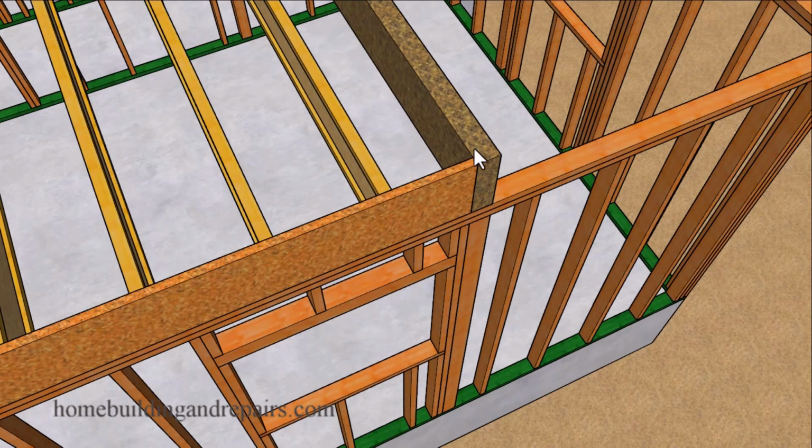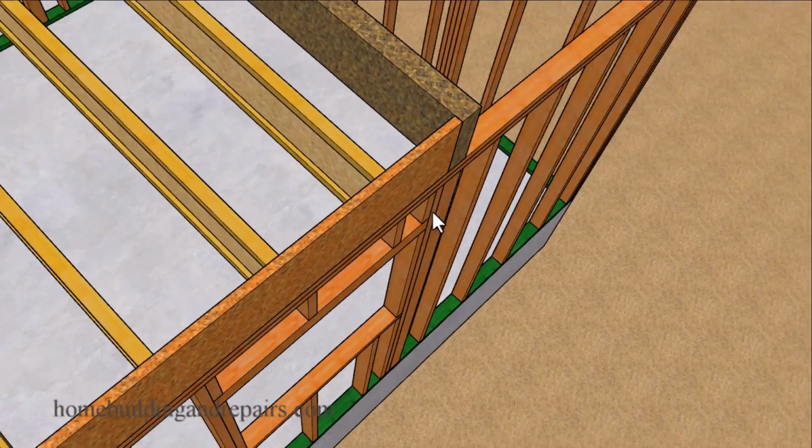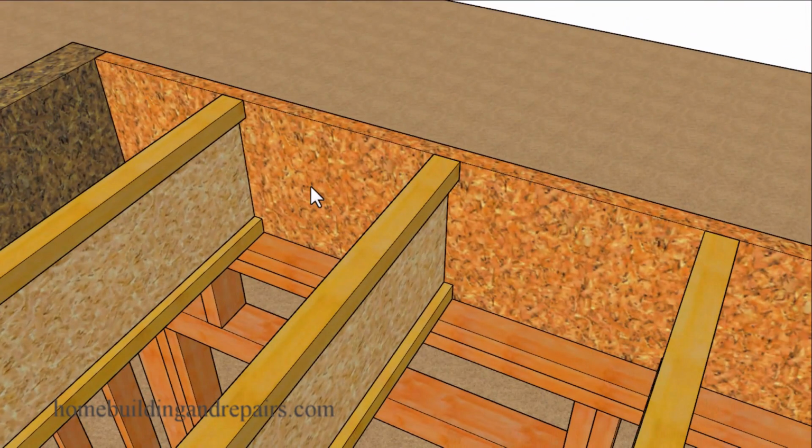And if you remember, on the other side, this beam was sitting on top of the bay window opening with the large header. And if you do run into a situation where we have the window over a little bit, and it's going to work out better for us to have a solid post under the beam instead of putting a huge header over the window opening with double trimmers, whatever the reason is, if it needs to stay there, leave it. But if not, sometimes you can simply move a window either to the right or the left of a structural post, a post support, if that's going to work better for your project also.